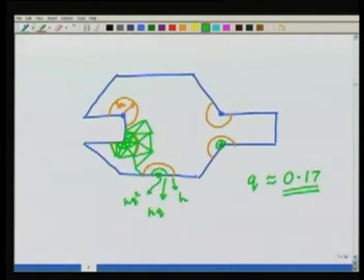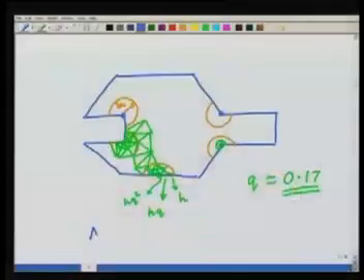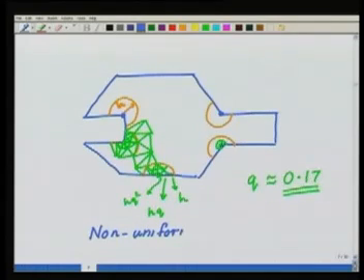So I will be getting my mesh like this. In the vicinity of the corners I make these geometrically refined meshes. Elsewhere, outside these corners, I can put large elements, nobody stops me from there. So I am making a non-uniform mesh.